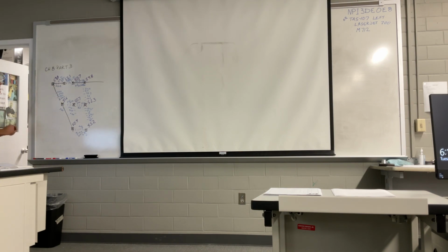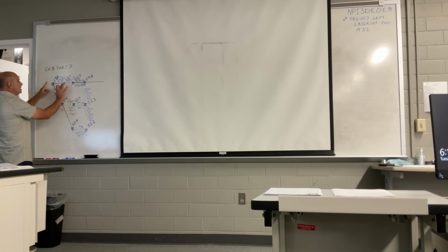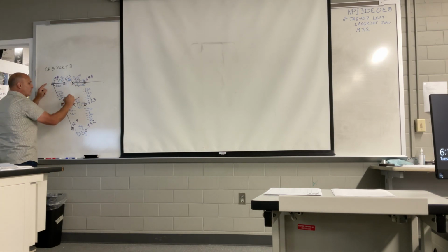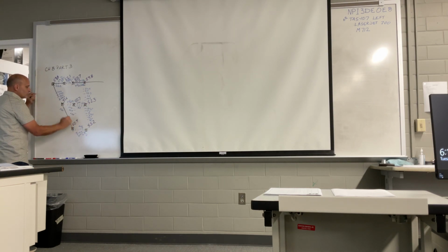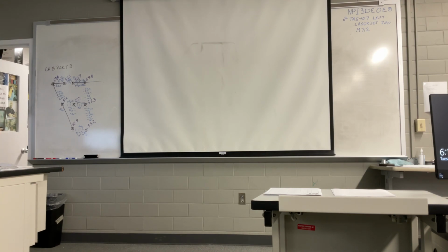Okay, there's 53. So what I'm gonna do is I'm gonna focus again on each little area, not just these 2 points. I'm gonna focus on this little bounded area. These 3 make a little triangular shape right here. These 4 make a rectangular square shape. When I get back over here, here's another little triangle around my property line. So we're gonna go horizontally and vertically, and it's as simple as counting from one to the next. Every time you hit your interval of half a foot, you just put a tick mark.